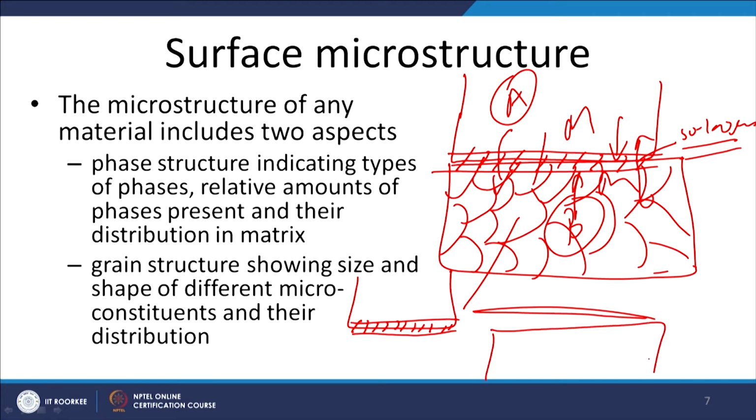Similarly, the structure and composition of the B side will have elements from the A side, and this structure is completely damaged. Therefore, the composition and microstructure of the actual sliding surface is more important to see the way by which the wear and friction behavior will be influenced. This is about the actual structural aspect which is produced during the sliding condition.